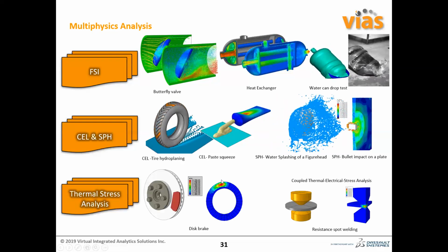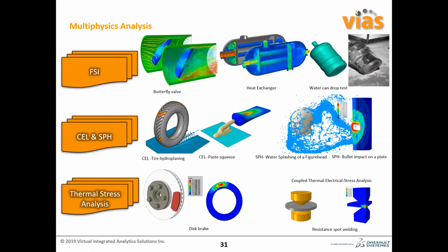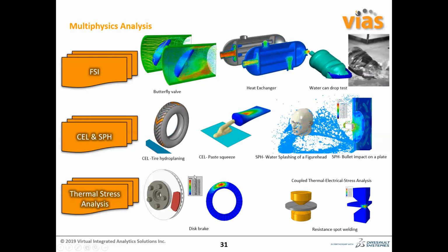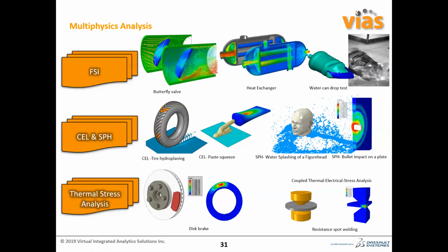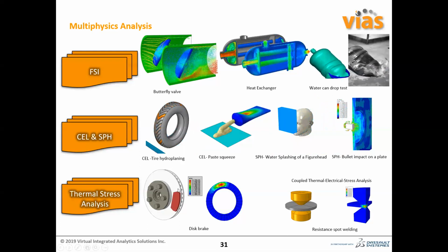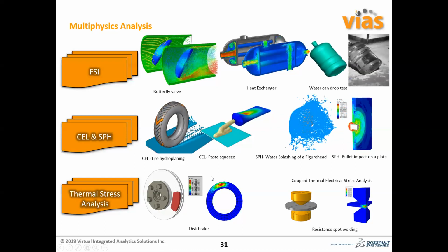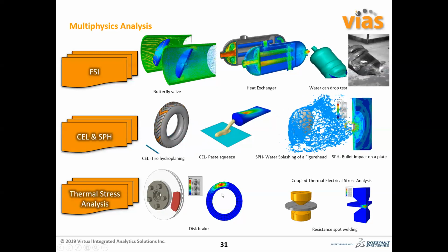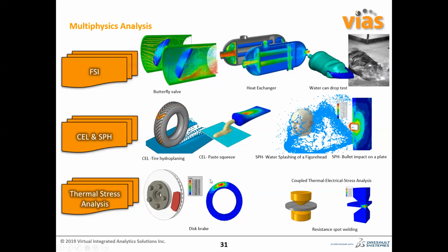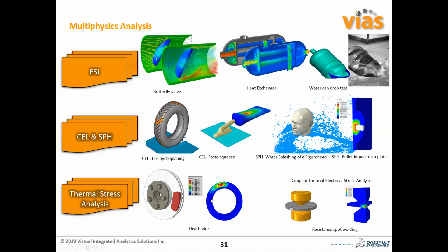And this is one of the scenarios. We know that SolidWorks has a thermal analysis capability, but there are certain thermal stress analyses where your heat generation happens because of friction. Like if you are pressing a brake pad on the rotor, because of the friction there will be heat generation. These are complex scenarios where the thermal-structural interaction is there, but it is really difficult to capture all those scenarios through the simple SolidWorks simulation capability.